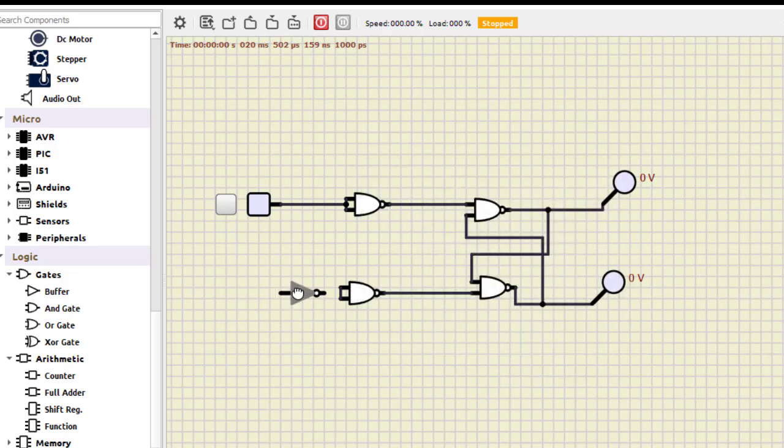I just keep it here, okay, and do this connection, and this is connected here, and of course we don't need this. So we only have one input, one output. Now this is the D flip-flop. We have converted the SR flip-flop into a D flip-flop. Let us start. So this is running. So input 0, output 0, input 1, output 1. So for 0 we get 0, for 1 we get 1. So this is how we verify the working of a D flip-flop. Now let us go to the JK flip-flop.